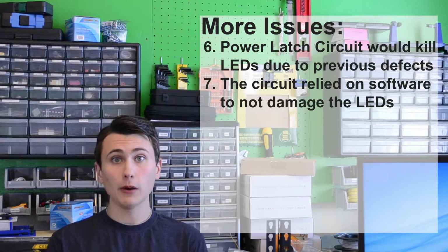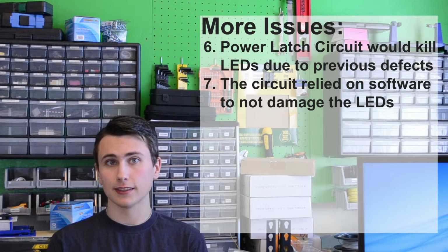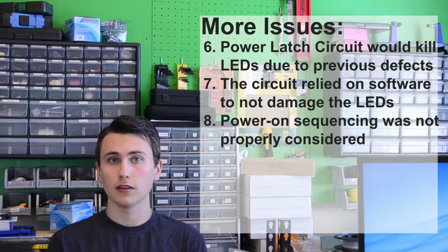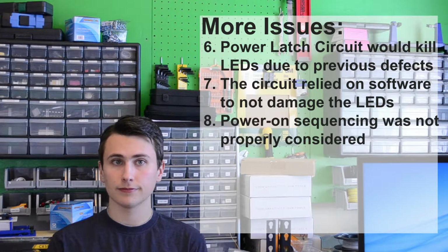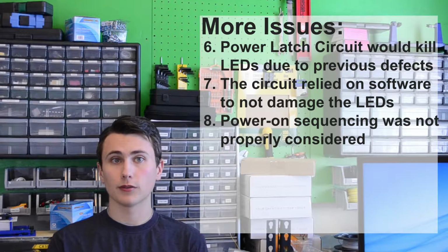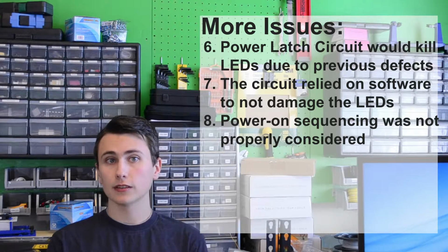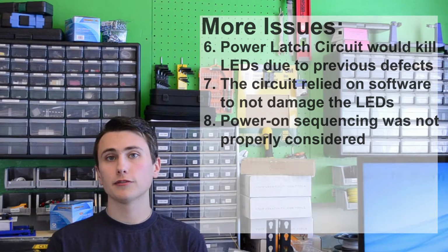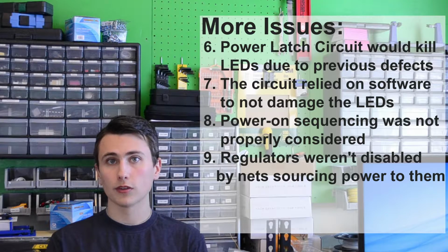2. Power supplies don't turn on instantly. You need to plan on the time where your power supplies are ramping from 0 to 100% of their set voltage. Also, if a signal is disabled with a non-ground potential, pull the signal up to the voltage supplying VCC to the circuit. That will prevent any condition where the chip is powered on but the disable is not on.